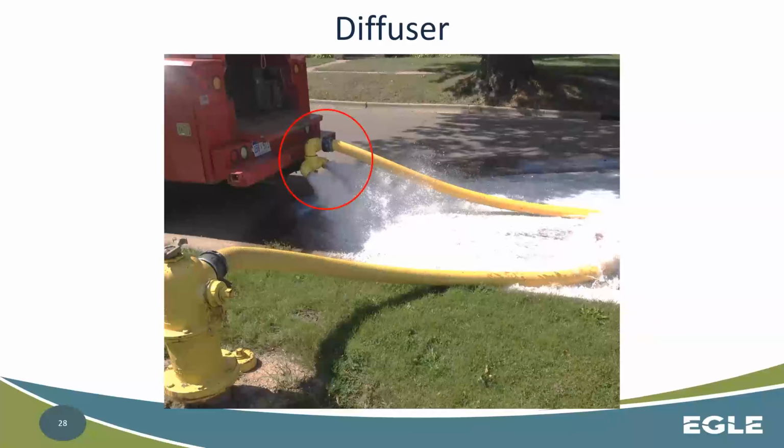Here's another device that can be used. As you can see, they've got a truck mounted energy diffuser or dissipator here. This isn't really a diffuser. A diffuser kind of blows the water into more of a mist style condition so that it's a little less aggressive. This is more of just an energy dissipator. So as the water is flowing off the pumper nozzle and hitting this, it starts to diffuse or displace that energy into multiple paths so that it's not quite as hard.